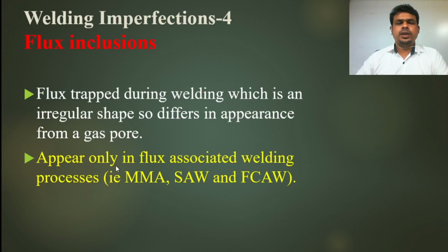Okay, it appears only in flux-associated welding processes: MMA, manual metal arc welding, SAW welding and FCAW welding. So with these three types of process, when you weld, flux can be trapped inside the weld and cause flux inclusion.